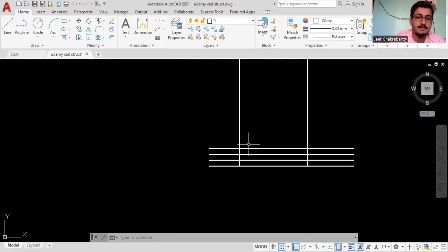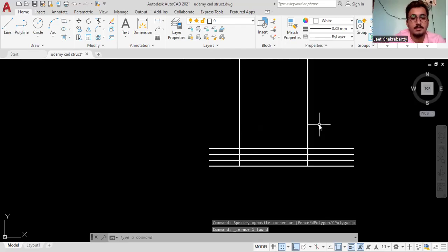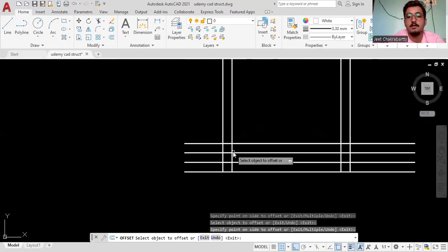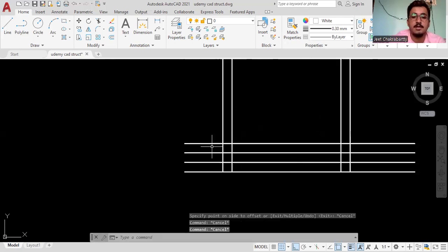In the side. What are we doing this for? Offset 5 inch. See, click on it and click on this side. So why is this offset being done? For the extra part, for the soiling and the PCC. Okay, hit the trim command, trim this upper part, it is not needed, and trim this also.